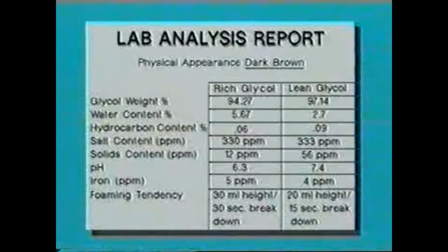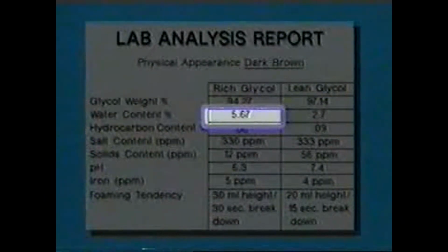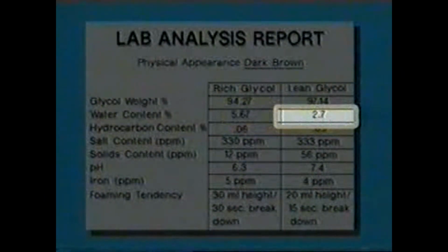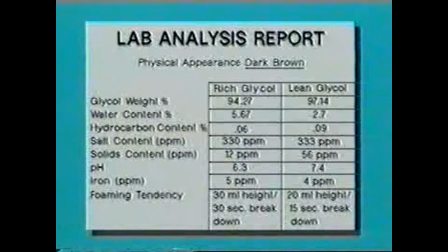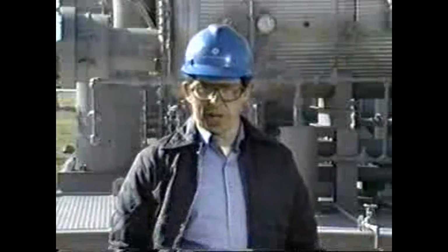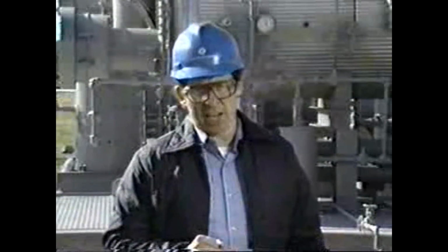Let's take a look at our sample. The water content for the rich glycol is acceptable. However, the lean glycol water content is too high. Again, this means that some adjustments may need to be made. Water content spread refers to the difference in water content between lean and rich glycol.